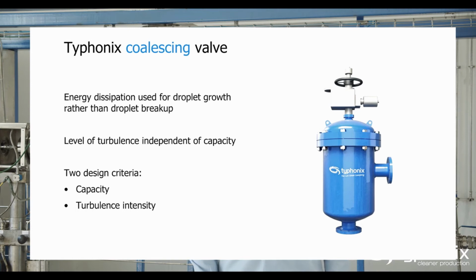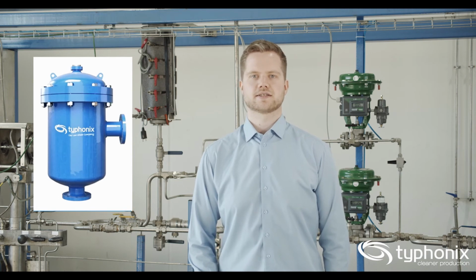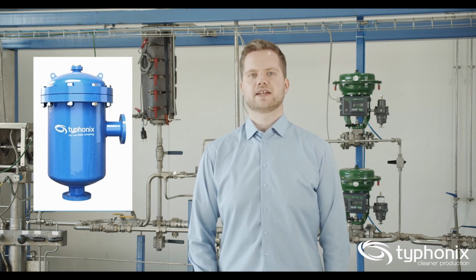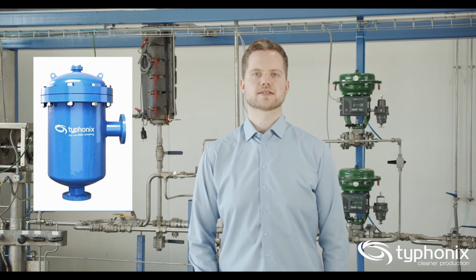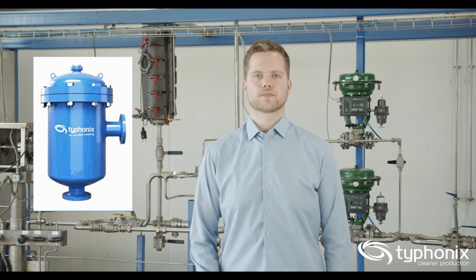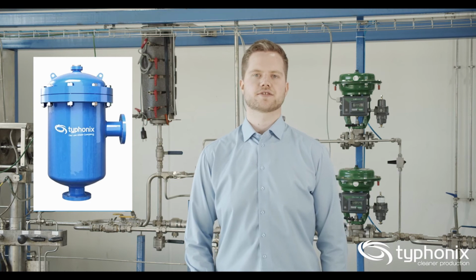And the design of the valve is such that the turbulence intensity which drives the coalescence can be designed independently of the capacity. So this means that we can get a valve which tackles the pressure drop and flow rates as desired, with, in addition, an optimized turbulence to get the best coalescence for the current fluid properties, droplet sizes and concentrations.